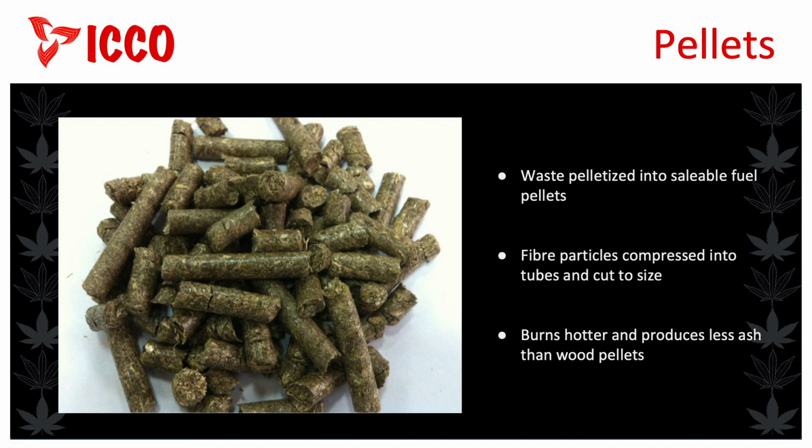The pellets are then weighed and bagged for sale. For higher production rates, a hammer mill can be used, which uses more energy but is much faster. In both cases, moisture will be required to achieve cohesion between the particles.